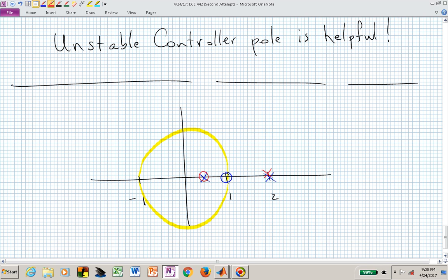It was nice when we canceled that, and now suppose that I locate my pole not between 1 and 2, but right at 2, and now my geometric mean calculation between the 0 and those two lengths is pretty easy. It's the square root of 1 times 1, and now my root locus is going to be a circle of radius 1 with center at z equal to 1. So these two poles come off of each other immediately, and they head around, they re-enter right at the origin. One goes to the 0 and the other one goes off to negative infinity.